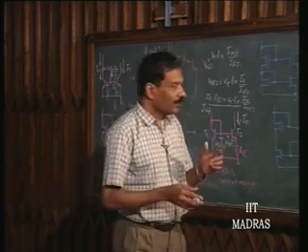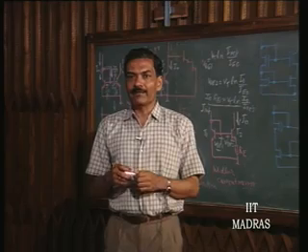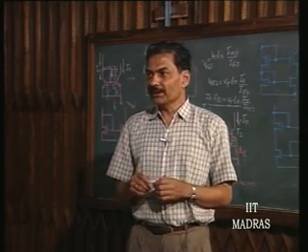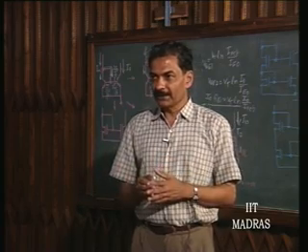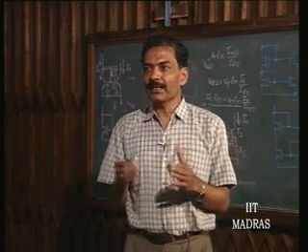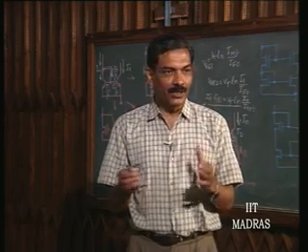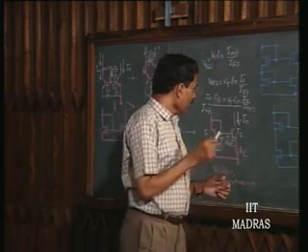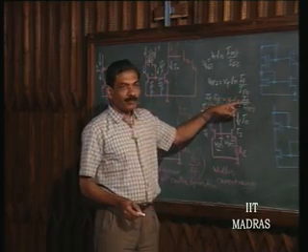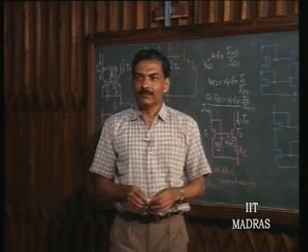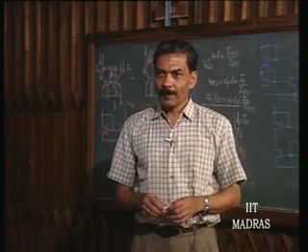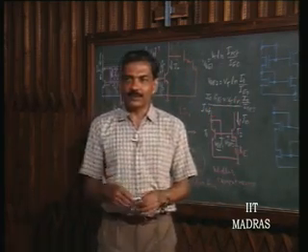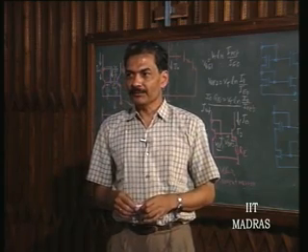Let us see how. Suppose you have 1 milliampere as I reference and you are required to get I naught, which is 1 by 1000th of it. That means, you are attempting to get a current of microamperes. Normally, you should have used mega ohm resistance. So, we already know in a design I reference by I naught as being equal to 1000. So, Vt log 1000, Vt is 26 millivolts at room temperature.